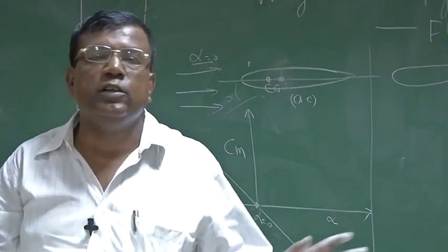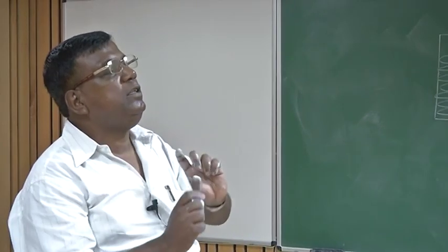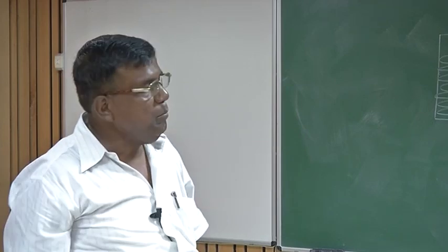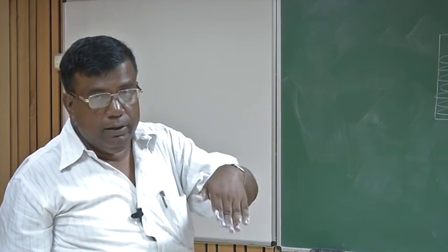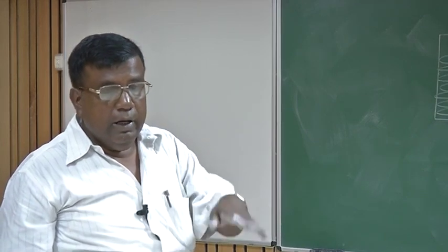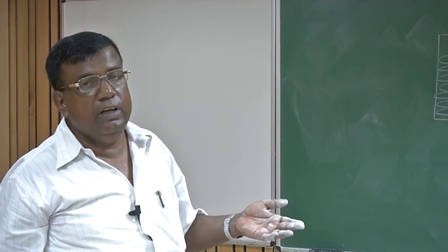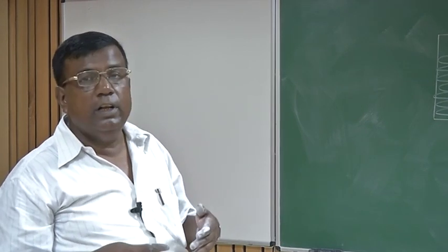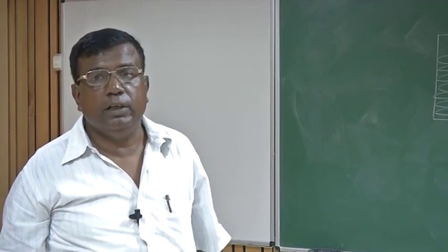No lifting trajectory you will get. Is it clear? Even if I throw it with some angle of attack, because it is statically stable, it will try to come back to the trim point alpha equal to 0. And since at alpha equal to 0 it's a symmetric aerofoil, nothing will be there as far as lift is concerned. So it will simply fall like a projectile.